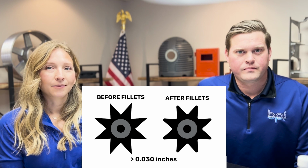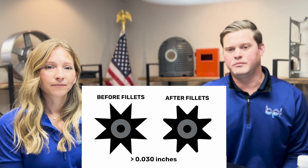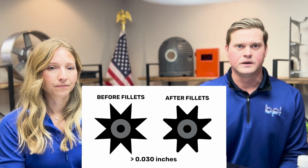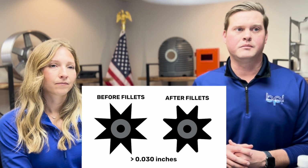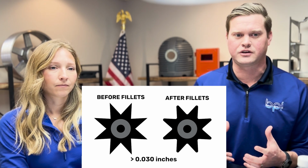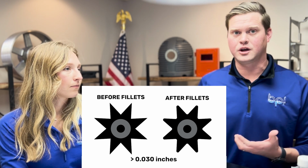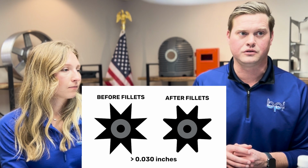Fillets and radii. You want to talk to this one? Sure. Yeah, so Rachel had talked about there are some technical sides of the casting, not just the wall thickness, that really help the castability, as we would say, of the product. So having your fillets designed correctly up front helps you on that castability side, to make sure you're getting a part out the way you want it to look, with the quality standards you're expecting to deliver.